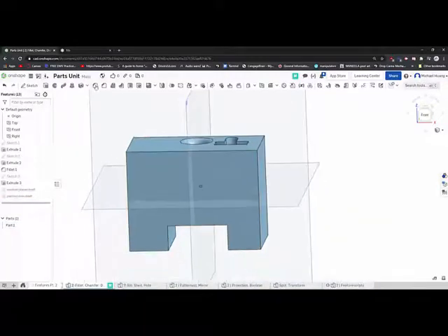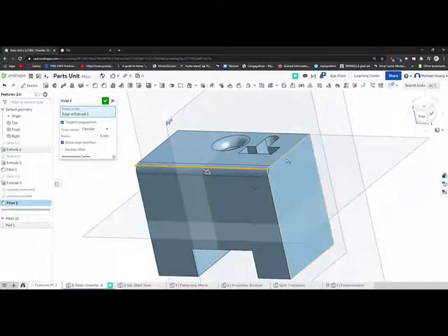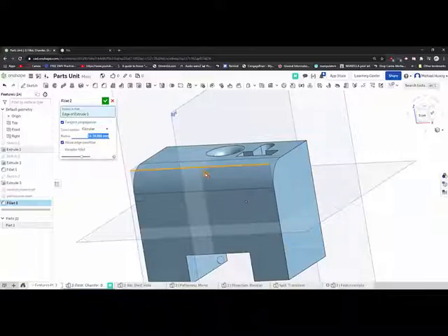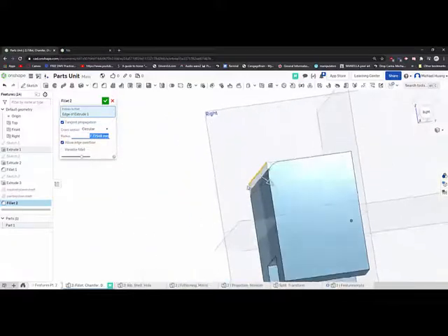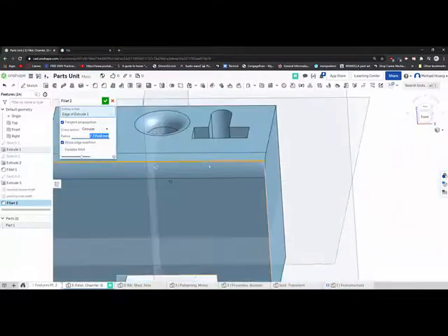Okay, next up is your fillet. This one changes sharp edges into rounded edges, like that. With this arrow, I can change the radius of my fillets. And you'll notice the cross section of your fillet, in this case, is circular. I have it selected. So it's going to create an arc, and that's why you're going to need a radius value, because an arc is defined by its radius. Right?